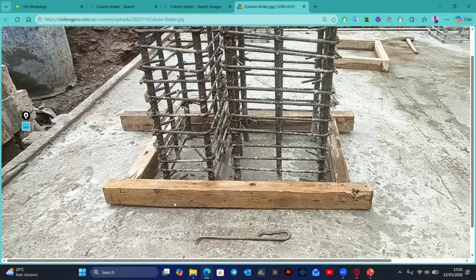Okay, so now this is the formwork I'm talking about. Before casting these columns, you need to provide a space between the reinforcements to come up with the actual cross section of that column. So we need a space where the aggregates are going to pass. This space left between the formwork and the reinforcement is the concrete cover.